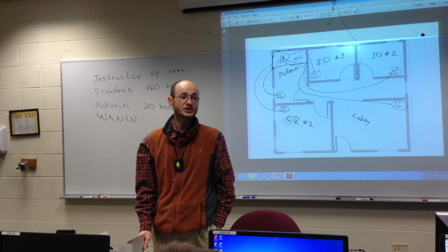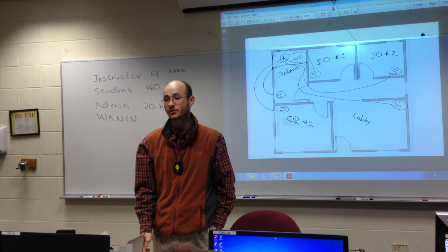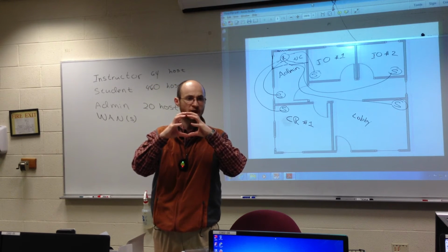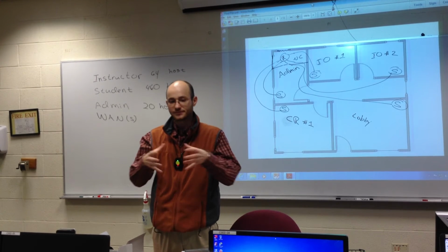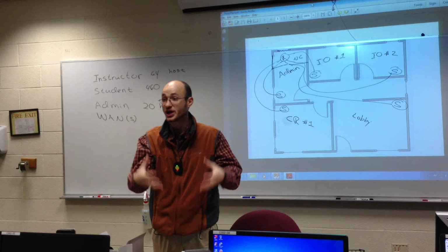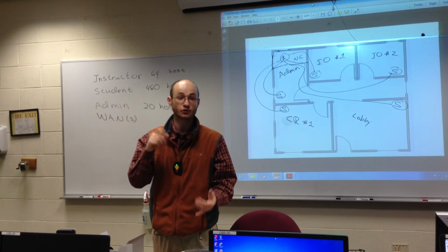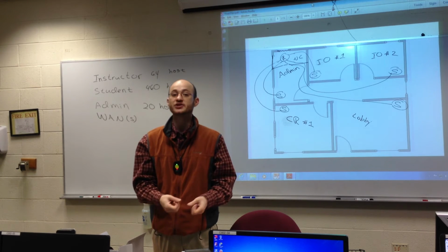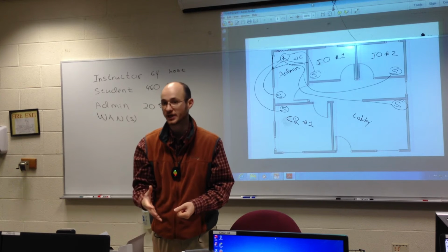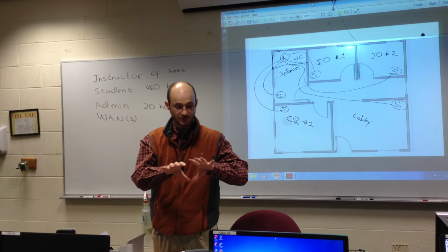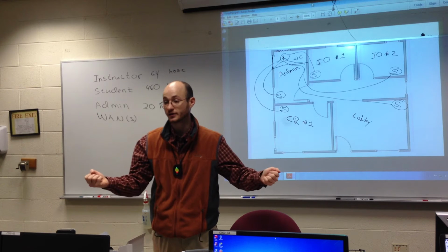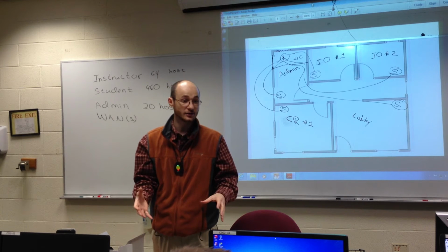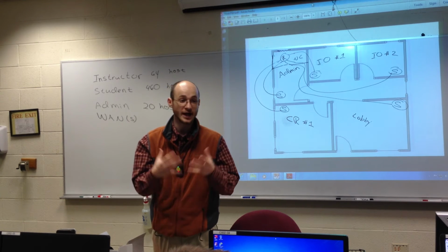So the question was, why are they using soap detergent or some kind of lubricant? If you're using conduit or a raceway and you're running a large amount of cable at one time, the cable increases its surface area, right? It acts like one big giant cable. And when you're trying to run that through some kind of drilled hole, conduit, pipe, or whatever the case may be, you're going to get friction. As you pull this cable, especially after 100 feet of it, it gets heavier and heavier, and the cable itself, internally, the copper could stretch, and you could pull it apart before you could even pull away the PVC jacket. So what they suggest is that you lubricate the outside.